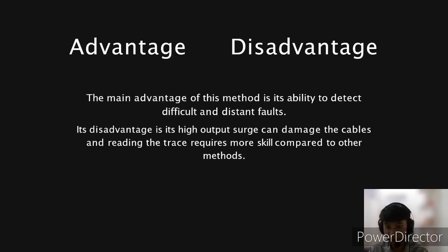Okay, the advantage and disadvantage of the pulse reflection method. The main advantage of this method is its ability to detect difficult and distant faults, while its disadvantage is that its high output surge can damage the cable and reading the trace requires more skill compared to other methods.